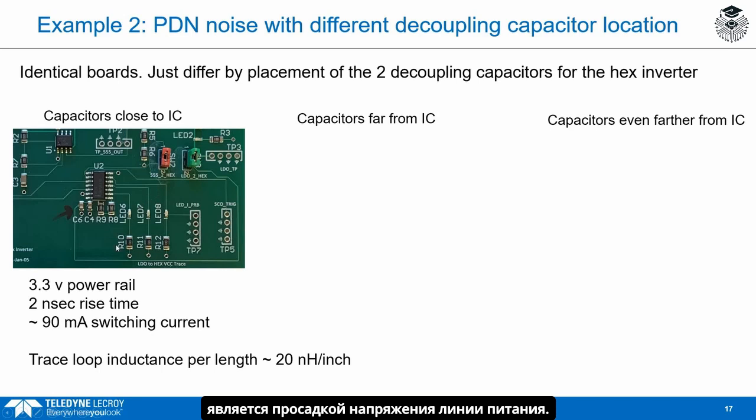that's the rail compression. Now in this example, we're going to look at the impact of that rail compression on the location of the decoupling capacitor, because we said if we want to reduce that inductance, we want to bring those capacitors as close as we can. We want to reduce the length and use wide conductors. Well, to illustrate the importance of that, here is the die. Here's pin 14.